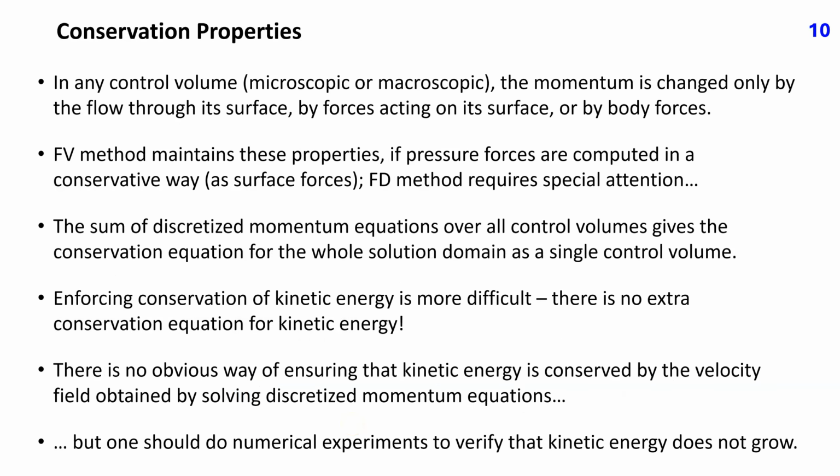In any control volume, whether microscopic or macroscopic, the momentum is changed only by the flow through its surface, by forces acting on its surface, or by body forces. A finite volume method maintains these properties if pressure forces are computed in a conservative way, that is, as surface forces. Finite difference methods require special attention if conservation properties are to be maintained.